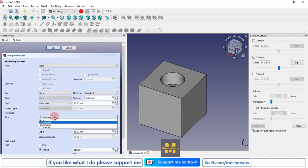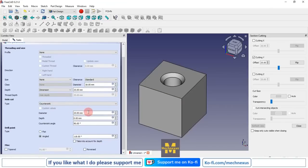So here instead of counterbore, let's select the countersink, and here we will give the diameter 30, inner diameter let's make it 20, and the rest of the things as they are. Like that you can give the taper, or you can change the angle to flat or angled.